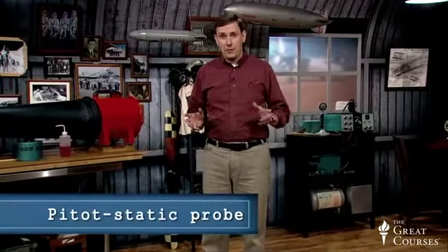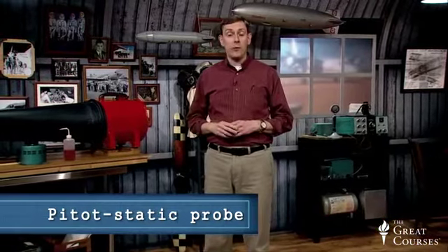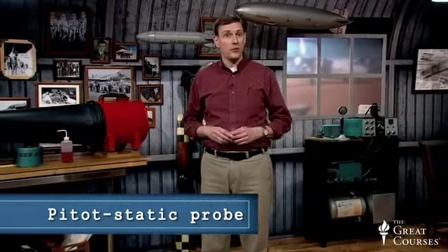The pitot static probe is an extremely useful tool for measuring flow velocity at a point within a wind tunnel. We'll talk about the theory of the pitot probe here for wind tunnels, but recognize that this is the same method used to measure the flight speed of an aircraft. It's a very simple and powerful technique.